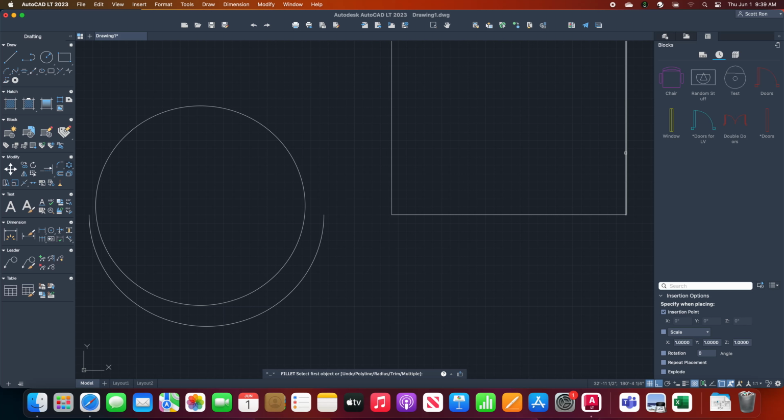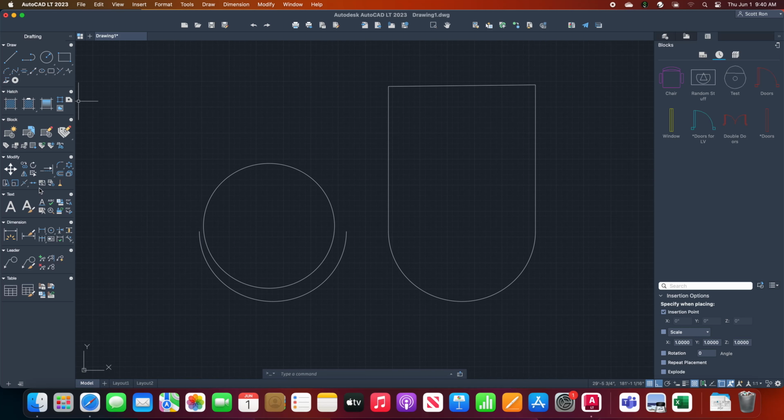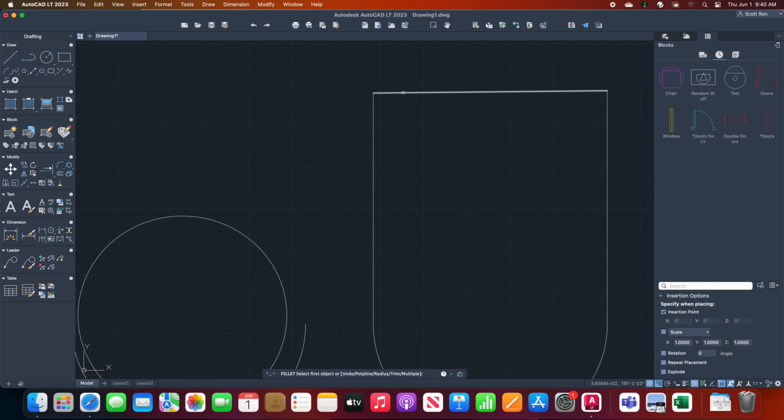So in that case, when you're trying to fillet, instead of going for 6 inches, it's just connecting them with an arc, and the length of the arc is 6 inches. No, that's what I'm saying. It's not doing that anymore, because it's too far a distance for that. It's just creating an arc that's appropriate and joining it. So then what about this arc is 6 inches? It's not. That's what I'm saying. But if you do that over here, a line that is intersecting or perpendicular, it will do it there. Now that radius is 6 inches.